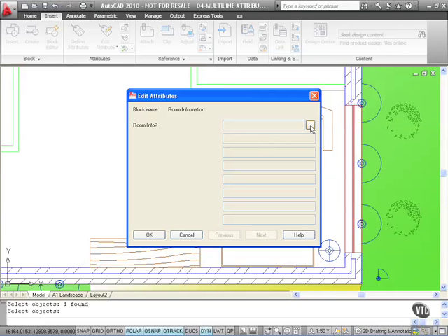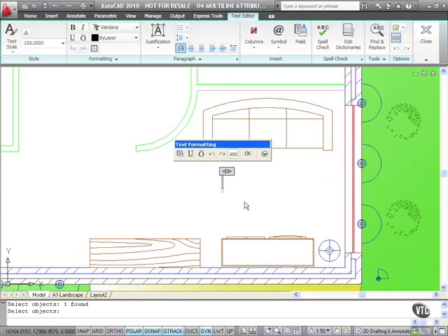Notice the dialog box appears here. Now, if I click here, it'll open the multiline editor. Remember, I said multiple lines in the Define Attributes. So I click there now, and my text formatting kicks in. So I've got my multiple lines. This is the living area. I'm going to type all of this in as I go. So that's living area, and I'm going to press enter to come down. It's got a 3-seater sofa. As I keep typing, it's adding multiple lines as I go. 3-seater sofa, and I'll actually put a space and then entertainment center.